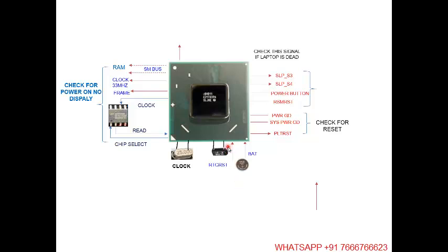But if the CMOS setup is still not saving, that means the PCH is bad. Here these signals are for the dead case, and these for CMOS not saving. Now we will see if the laptop powers on but does not give a display.